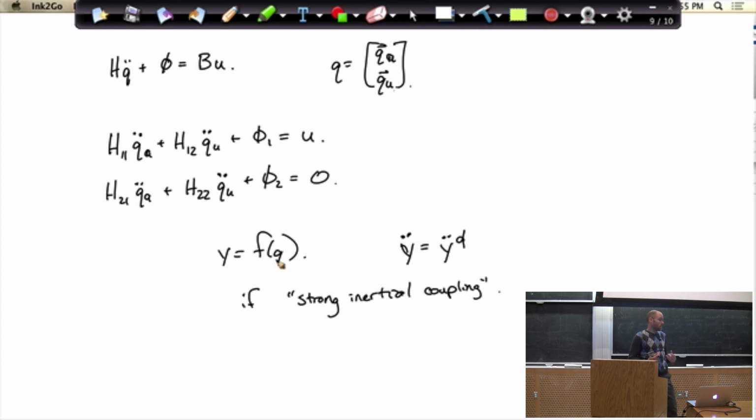But it turns out this notion of partial feedback linearization is very general for the manipulator equations. In general, if you have n motors, or m motors, let's say, I normally use m for the motors, then I can roughly control m quantities of my system with partial feedback linearization. The time it's not going to work is, let's say I have a motor attached to this desk, and I want to command something way over there, and they're just not attached at all. That's not going to work, right?